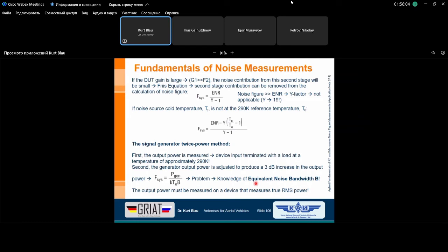And we cannot only measure, let's say, the transmission curve of our power amplifier and say, okay, the normal definition is we have the maximum, and to lower frequencies and to higher frequencies we have 3 dB less, or 1 divided by the square root of 2 less regarding the voltage. Regarding the power, it's the half power, the lower half power and the upper half power over the frequency. And between these 2 points, it's normally determined as bandwidth.